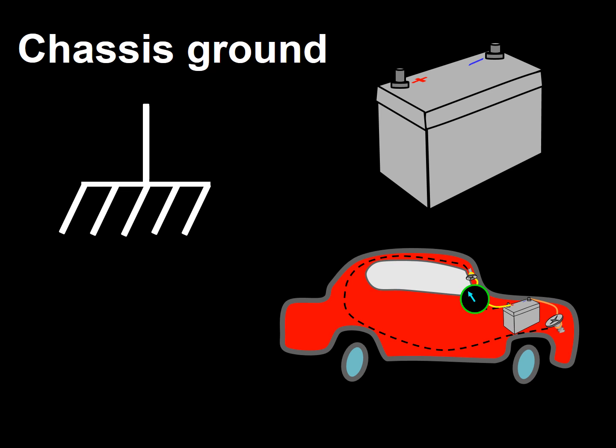This arrangement offers a return path for electricity. Offering a return path for current is the only function of a chassis ground in a car, since the connection to Earth is neglected because of the high resistance of the rubber tires, and the volume of the chassis is not big enough to dilute voltage to the same extent that will be diluted by the planet Earth.